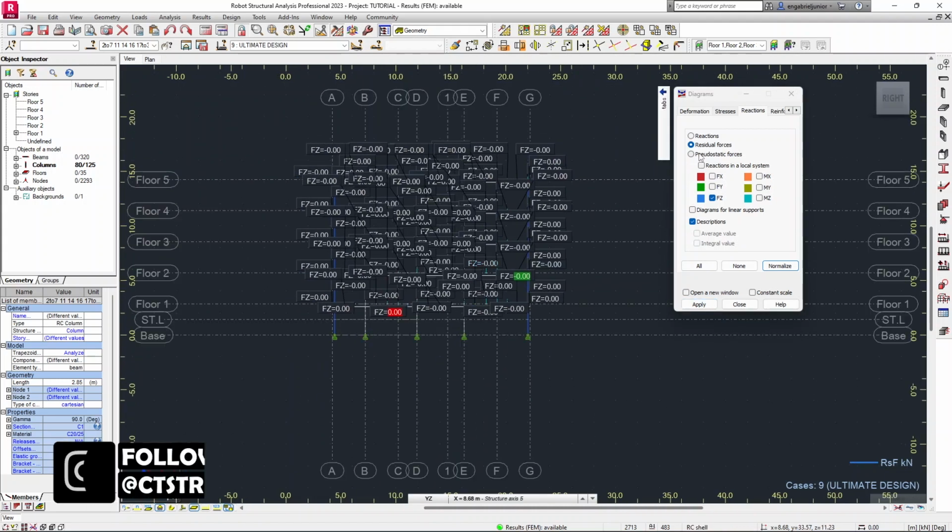Moving on to pseudostatic forces. Now these are nodal forces arising from loads indirectly applied to the structure. Now this could be in form of seismic loads or wind loads, or other wind generated loads which are not assigned to any part of the model. As we looked at previously, how we are assigning loads to the different elements, now these loads are not assigned in that manner, rather they are externally assigned.